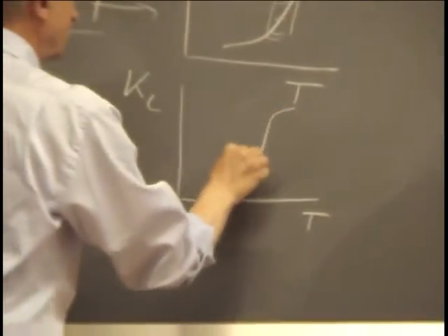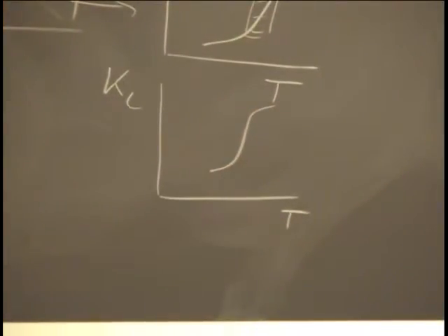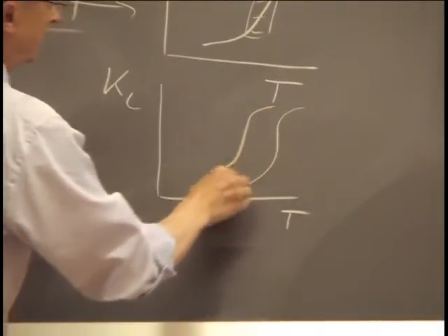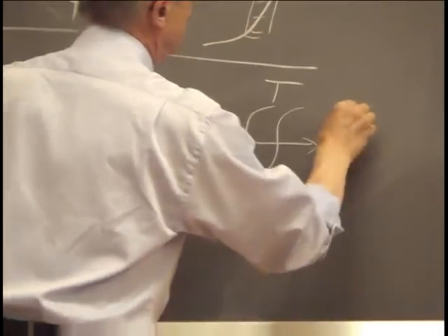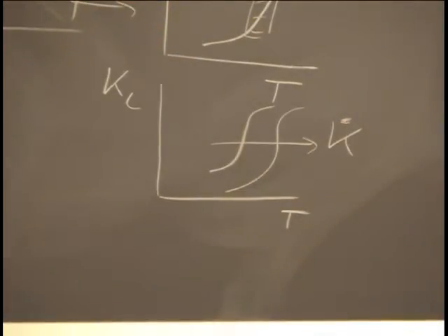But the point is also that with these steels, the transition here is affected by the loading rate. So when you have a high loading rate, the steel embrittles and it shifts the transition curve, simple K dot, so loading rate. It shifts the transition to higher temperatures.